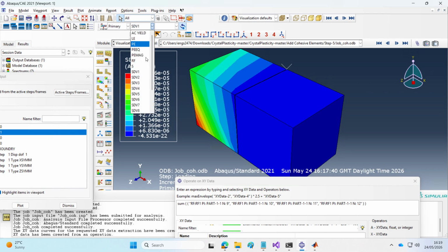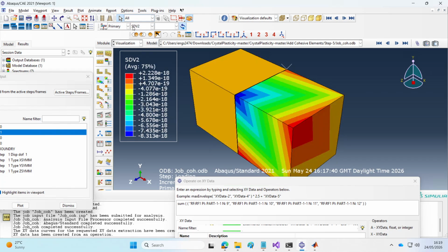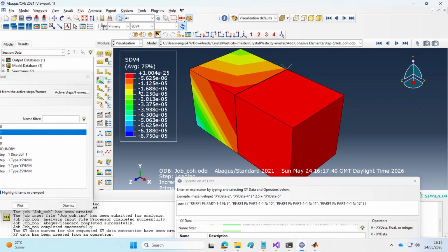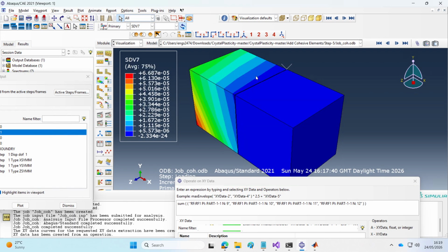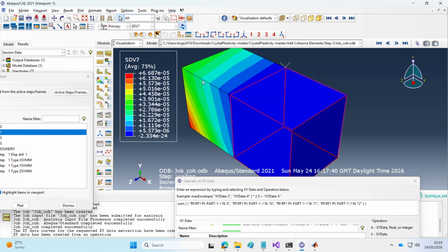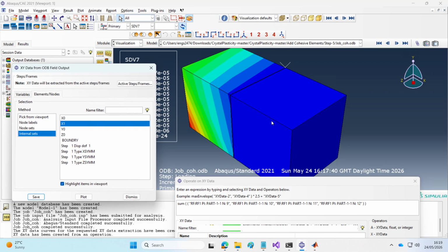If you look at the strain rates, there is some slip going on in one of the grains. Maybe this grain is softer because it's cube. This is the Goss grain. It's not really deforming. So this grain is mostly rigid, but the other one is deforming. There's slip going on in this one, but not in this one. So it just breaks when it reaches the magnitude. It behaves like an elastic material.